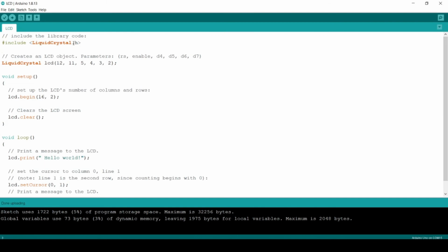The very nice thing with Arduino is that it doesn't ask you to add the LCD library, because whenever you download the Arduino IDE software on your laptop, the Arduino developers have already built the LCD module into the software. So you need not add the library of this LCD module. It will be there once you install the Arduino IDE software.